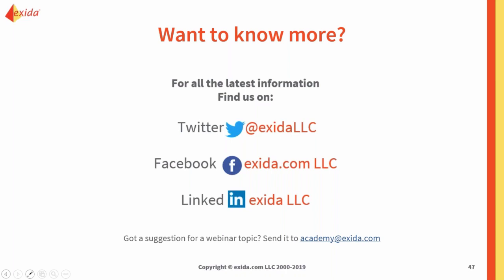And the next question we have, when we ask a manufacturer to provide the full assembly SIL cert, they claim they have a charge for that, so we end up getting their individual certs rather than the whole assembly. Is this acceptable common practice? I don't know what manufacturer you're dealing with, so I don't know their practices or what all's going on with that. However, if you are getting the certificates for each individual piece and you're putting them together and you're doing the calculations yourself, that is absolutely acceptable per the standard. As long as you're doing the verifications, you're making sure that everything is included, that's absolutely fine.